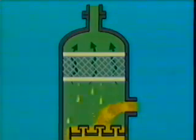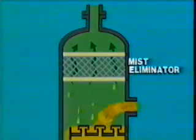Above the top tray, a mist eliminator in the top of the contactor will remove any entrained glycol particles in the gas stream that have not settled out. This prevents liquid glycol from being carried out of the contactor and into the gas discharge line, commonly referred to as carryover. Carryover occurs when glycol contamination causes foam buildup. Carryover also happens when the gas rate is high enough to agitate the liquid on the top tray so that a foam forms that is too thick for the mist eliminator to handle. The gas rate must be reduced to eliminate carryover.